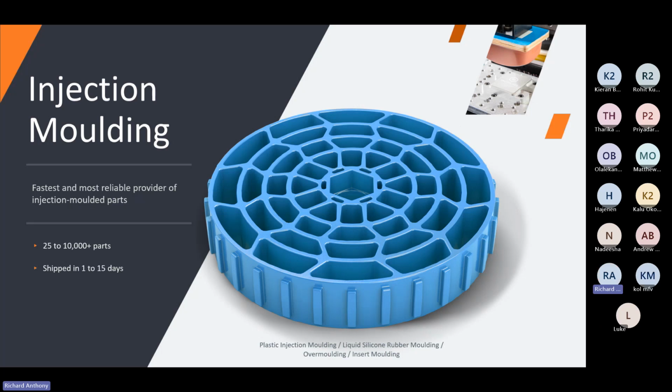All of the mold tools are CNC machined. We work with aluminium for the mold tool, so we can produce that mold tool very, very quickly. But then the actual molding process itself is a completely normal traditional molding process. Normal injection molding presses, normal injection molding materials, all the same considerations from a more traditional injection molding process. We're just working with a mold tool that's been produced on a very fast lead time.